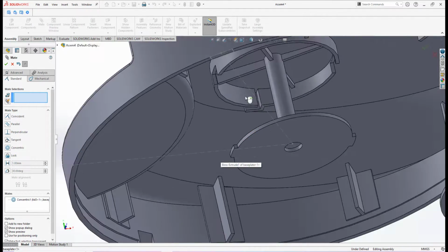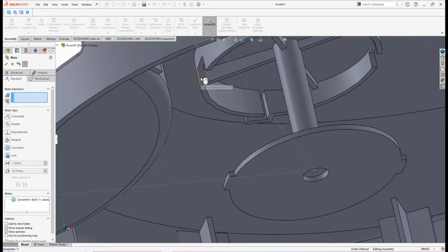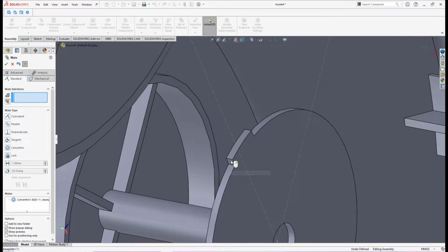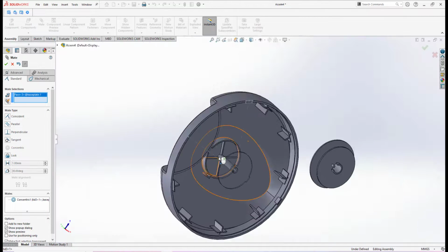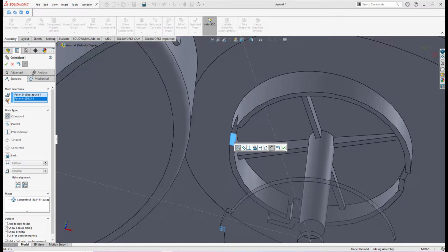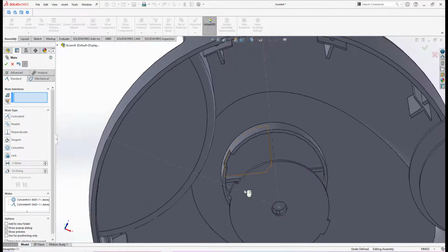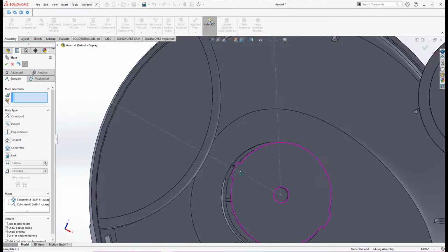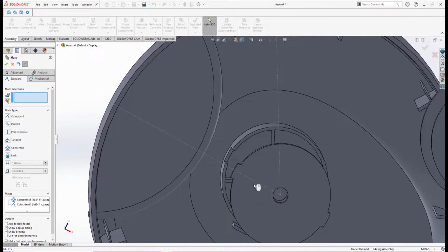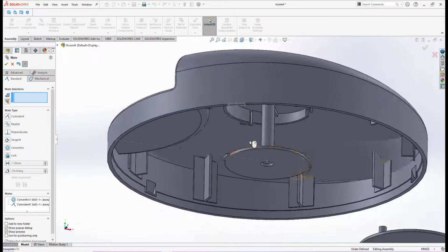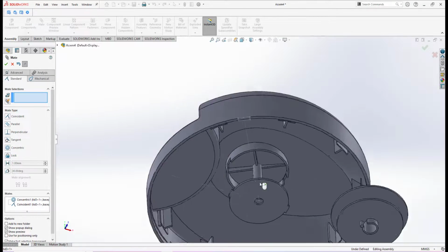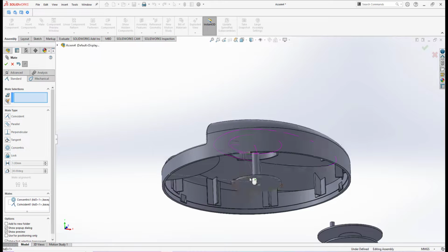But now for the other setting, if you look at this base plate, we have a key here, and it must mate to that slot vertical face. So I will select this face of this base plate, which must mate with the slot face here, and I click OK. What it shows here is that it is in line in position because that face and that face are coincident. So for my next mate setting for this base plate, I need to select the top surface to be laying on the spring, but it's kind of hard for me to select the face.